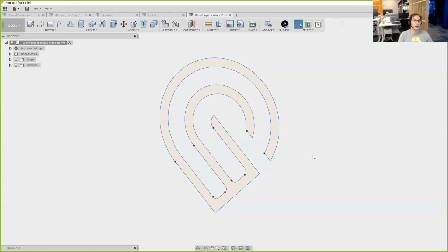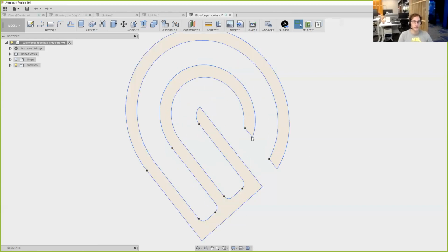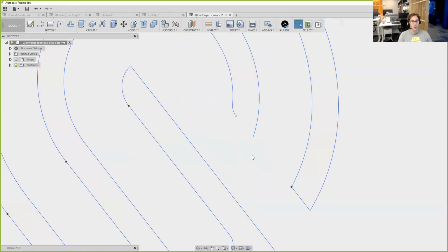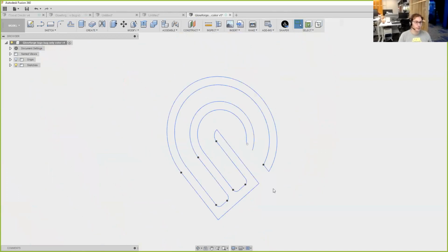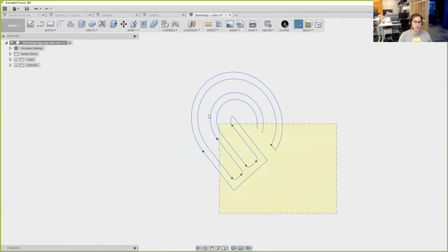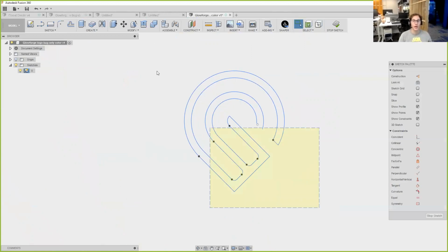So for example, if when I brought this thing in, it's missing, let's say this line right over here, notice what this looks like right now, right? I still have all those same blue lines. By the way, I could turn them green by highlighting everything. Actually, we need to edit the sketch first. Let's go and edit the sketch. I could highlight everything and lock it, and so now everything is green.